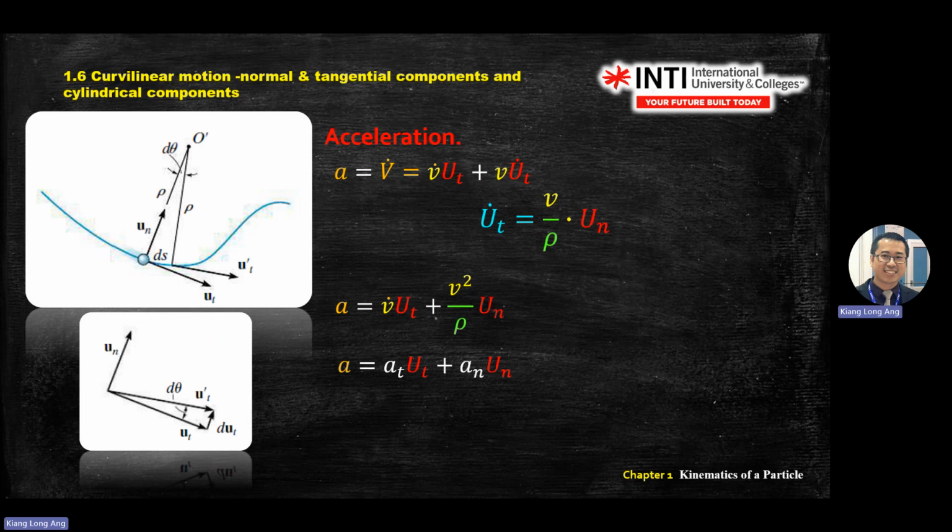Follow the curve direction. This is the n. Now say you're given a velocity value, v equal to 10 meter per second. Straight away, use your ruler, follow the tangent direction. Because this is 90 degrees, draw the velocity along the tangent direction.